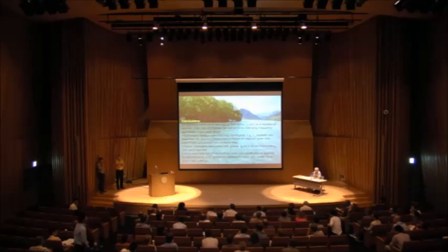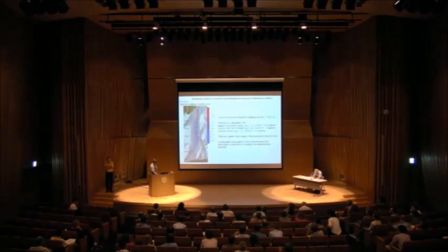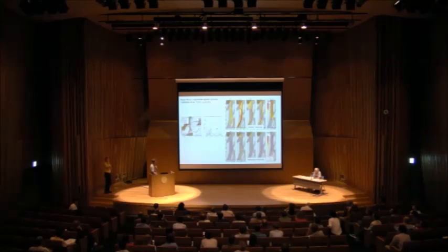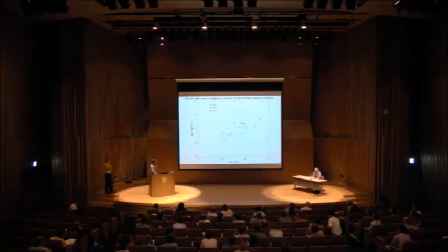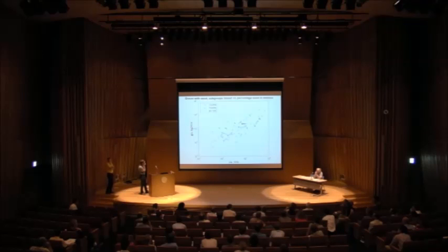So a question for both of you, but first for Colin Rennie. Could we flick back a couple of slides? Which one? Keep going. Yeah, that one. Okay. Yeah, that one I like. So I may be making this up, but I think Paul Carling told me once that when you measure bed load, if you get more than 1 kilogram per meter per second, there's probably something wrong, because that's about as much moving carpet of gravel that you get through 1 meter bed width in 1 second.